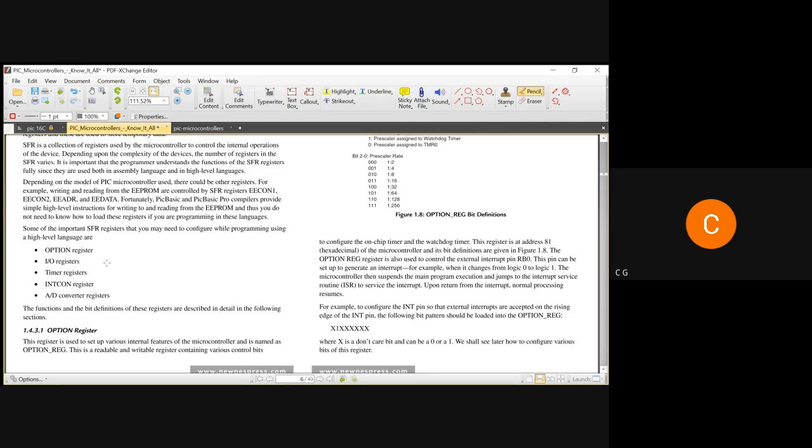Similarly, whatever the microprocessor or microcontroller is going to do with all these, it has to be notified or registered somewhere, with the help of a flag as a common name, where this 8-bit flag register will have certain zeros and ones.